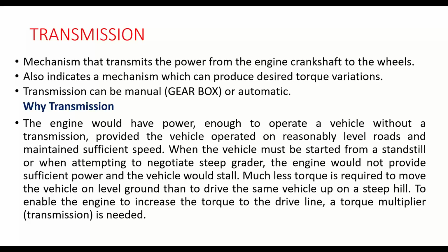say, for example, you want to drive the vehicle on a flat road itself, no question of any hills or steep curves or load variations. But what happens, all the time the engine produces very high torque. Say whatever 150 newton meter or 100 newton meter the engine is designed for, it keeps on producing the same torque irrespective of load, irrespective of speed. So the efficiency of the vehicle goes down, and practically you cannot imagine a vehicle without any transmission system, because you go to any place, you cannot get a flat road throughout your drive conditions.